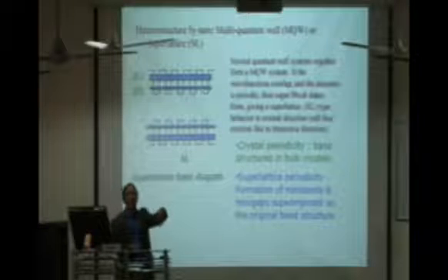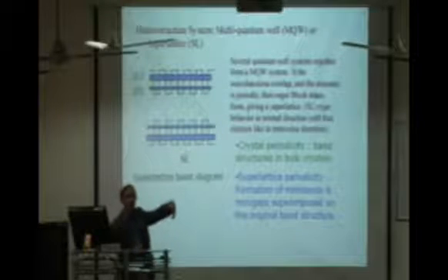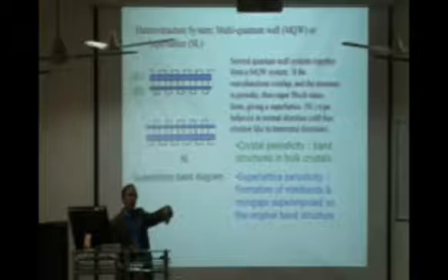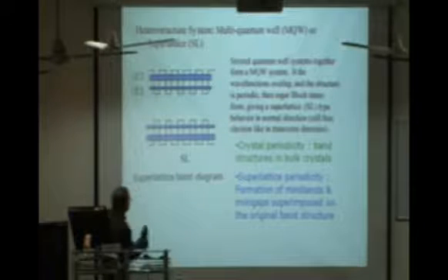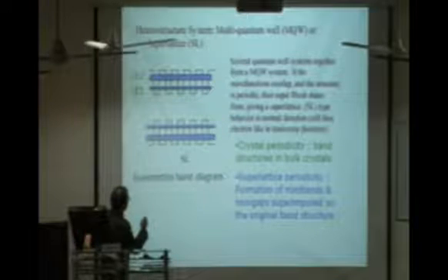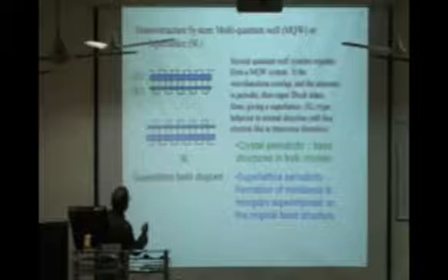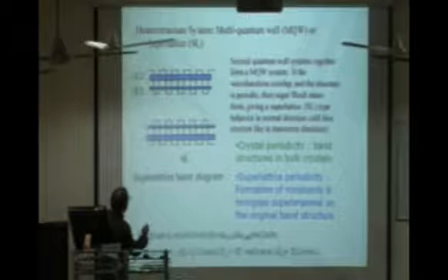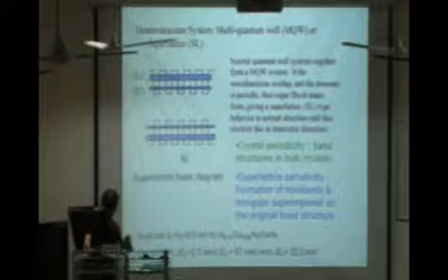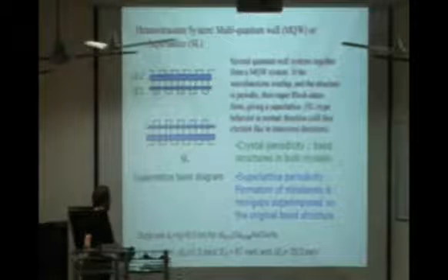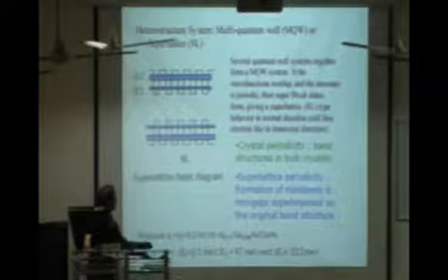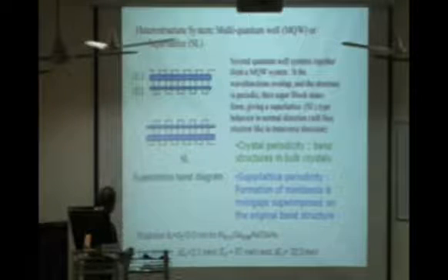So if you can make a system like this, you have tailored a material which has inter-subband transitions or some kind of a mini gap between the two levels in the conduction band, and again the band gap between the two levels in the valence band. And we have calculated some of these values using some combination of aluminum gallium arsenide and gallium arsenide, and the thickness of both the barrier and the well is in the range of 9 nanometer.